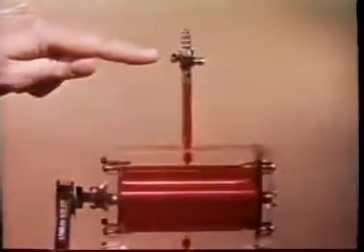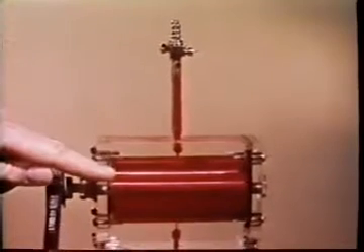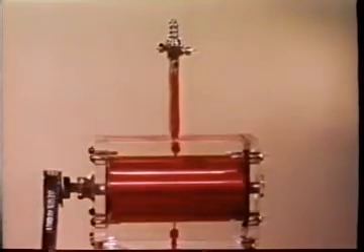By sealing the journal from the atmosphere, such a strong negative pressure is built up in the diverging section that cavitation bubbles appear. The bubbles get longer as the speed increases.